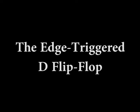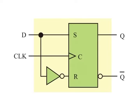The edge triggered D flip flop. The D flip flop is useful when a single data bit, 1 or 0, is to be stored. The addition of an inverter to an SR flip flop creates a basic D flip flop, as shown here. Notice that the flip flop in the figure has only one input, the D input, in addition to the clock.